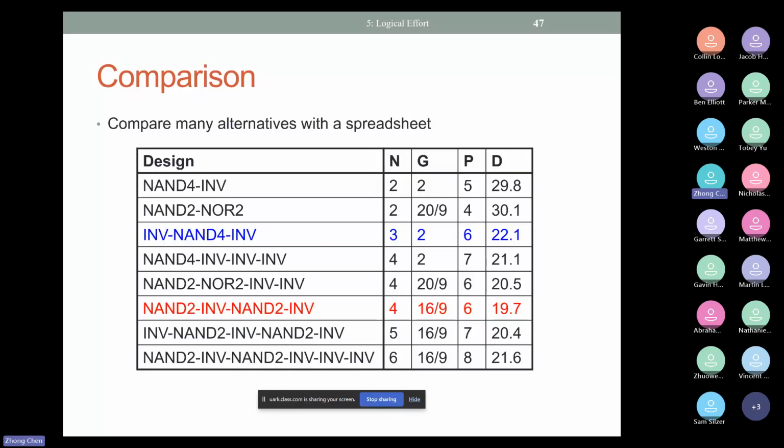And then we talked about, okay, if I don't know the number of stages, I don't know the design, I don't know what kind of gate, you have the flexibility to change the gate, and I just know the input capacitance and output capacitance and what type of gates. Well, I can use this method, the best number of stages design, using rho equal to 4, which is the best stage effort equal to 4, to estimate the best number of stages.